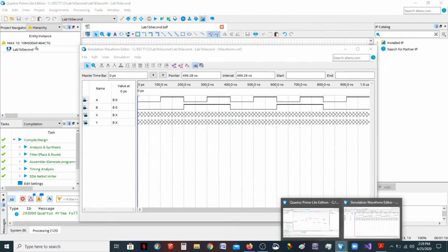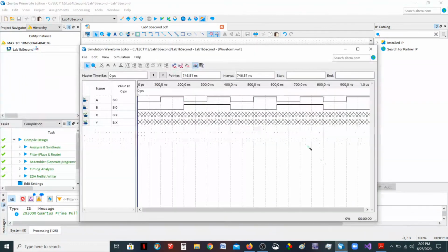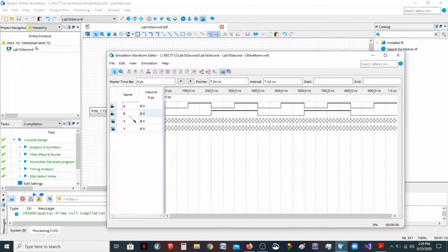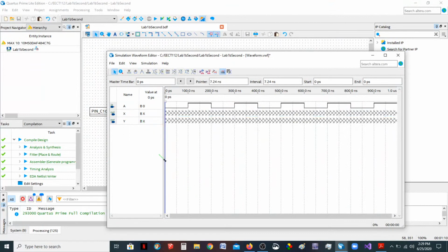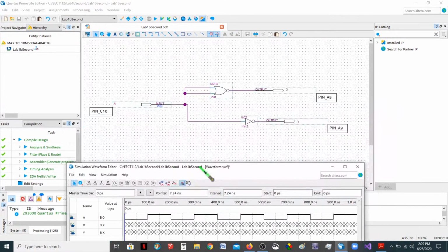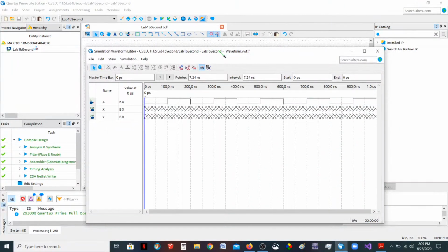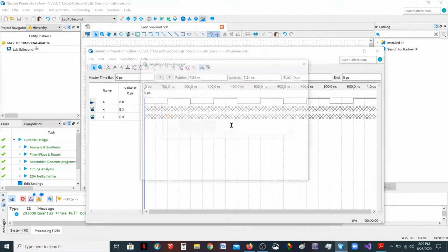I don't have to make any other adjustments to it, okay, because I still just have, let's see, what do I have here? I can get rid of the B right now, actually, because I don't have a B input anymore. So I can just select that, right-click, delete. My delete key doesn't work because I spilled something on my keyboard, so I have to right-click and delete everything. But anyway, now this reflects that we have an A, X, and Y. That's the only thing I need to do here, and I can go ahead and say, run timing simulation. Yes, I want to save it.